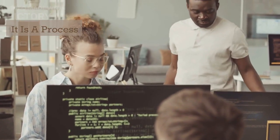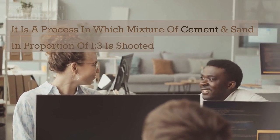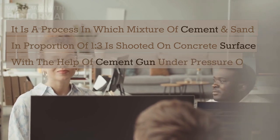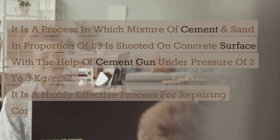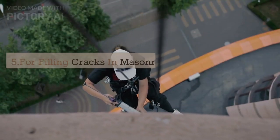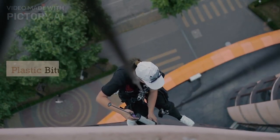It is a process in which a mixture of cement and sand in the proportion of 1:3 is shot onto a concrete surface with the help of a cement gun under a pressure of 2 to 3 kilograms per square centimeter. It is a highly effective process for repairing concrete walls or damaged surfaces. 5. For filling cracks in masonry structures, the type of bitumen used is plastic bitumen.